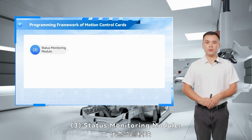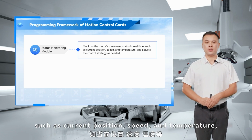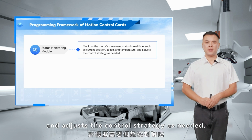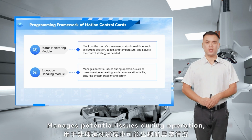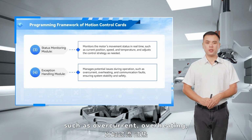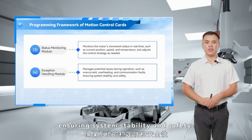3. Status monitoring module monitors the motor's movement status in real time, such as current position, speed, and temperature, and adjusts the control strategy as needed. 4. Exception handling module manages potential issues during operation, such as overcurrent, overheating, and communication faults, ensuring system stability and safety.